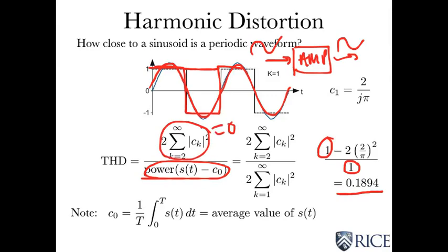Well, amplifiers have some moderate amount of distortion, and so you want one number that quantifies how linear it is, and they use total harmonic distortion for that through a series of test equipment. Harmonic distortion of even 1% is considered pretty large. In fact, all audio amplifiers are specified through their harmonic distortion.